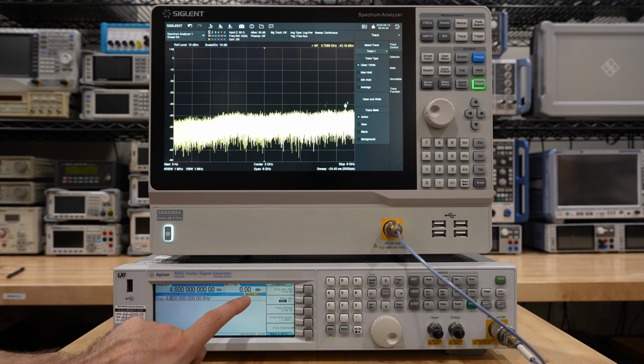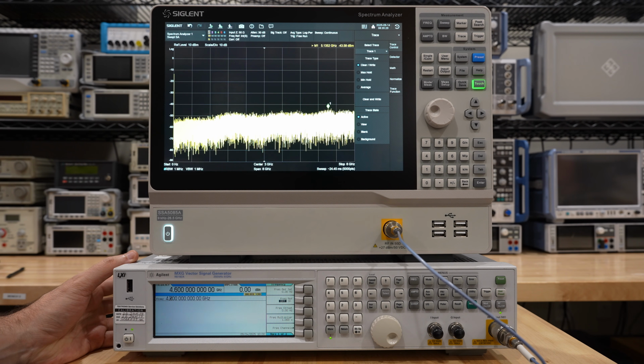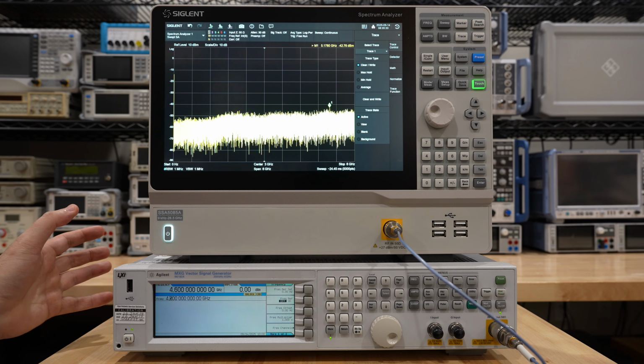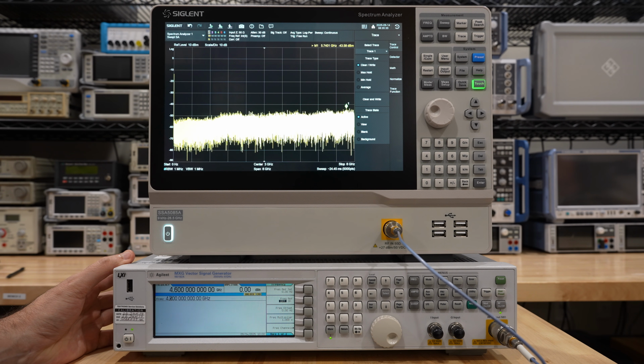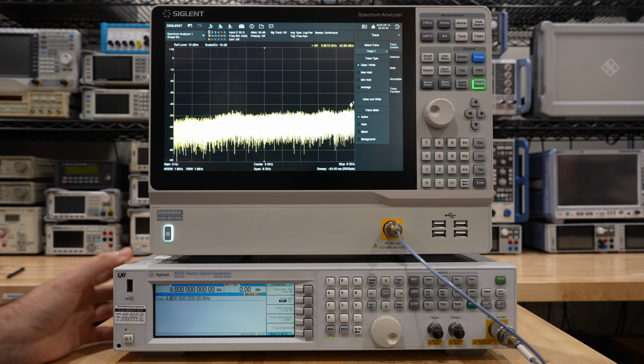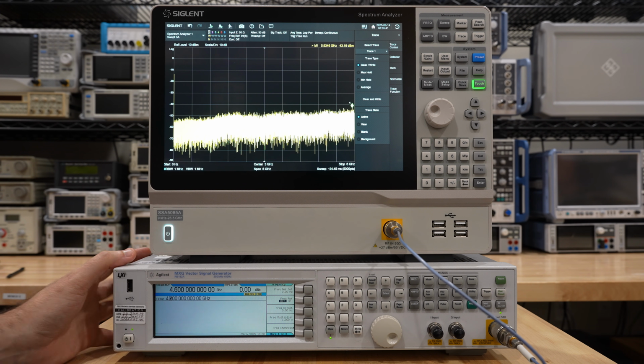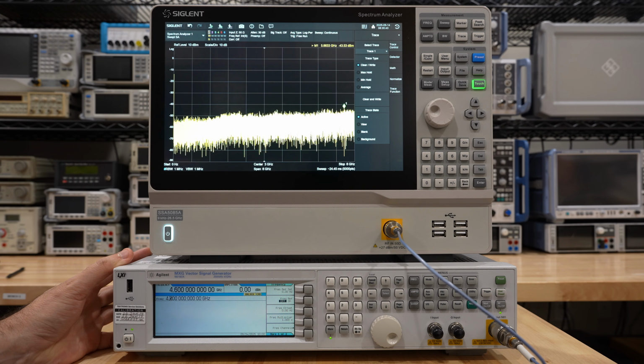And over here, an error has popped up, which says a Fractional-N PLL has been unlocked. In fact, this unlock is so catastrophic for this PLL that the frequency has completely disappeared because it's probably sitting somewhere and it's not passing through the bandpass filters for this particular frequency it is trying to generate. So you're seeing nothing at the output.